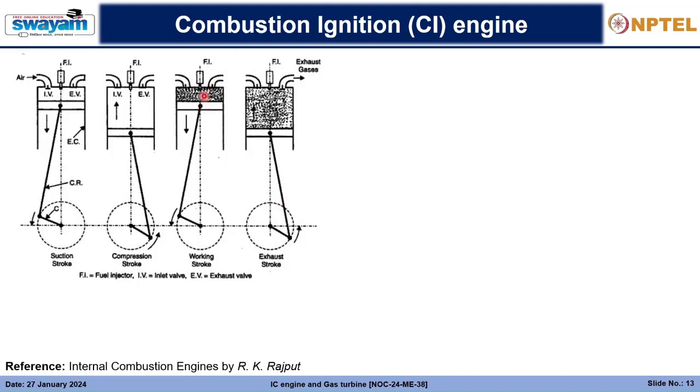So the only difference is that the fuel is injected directly into the system, but in spark ignition, an air fuel mixture was introduced into the system, and the air fuel mixture was mixed in the right amounts by a carburetor. But nowadays, the carburetor is completely obsolete. It is being removed from the system because it is a little bit bulky in nature.